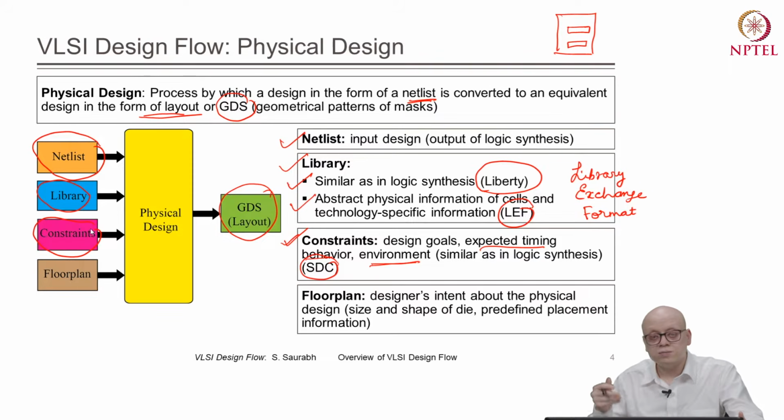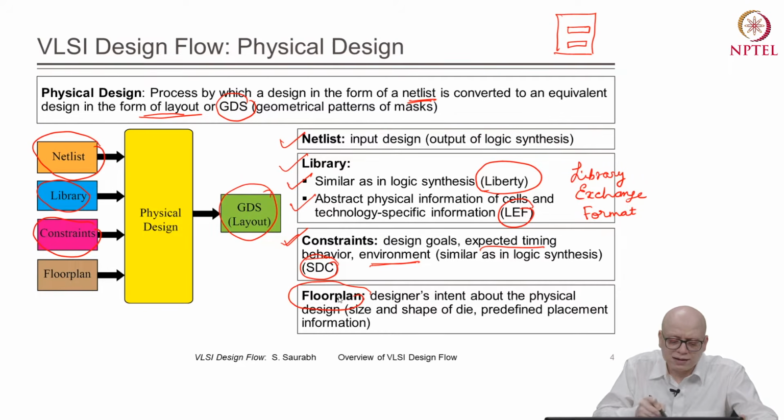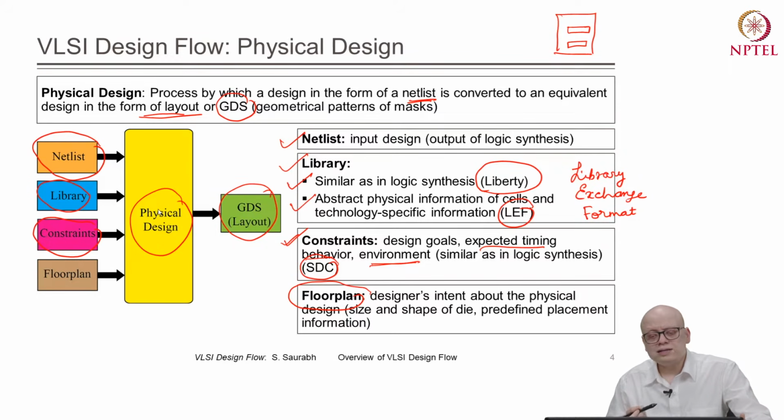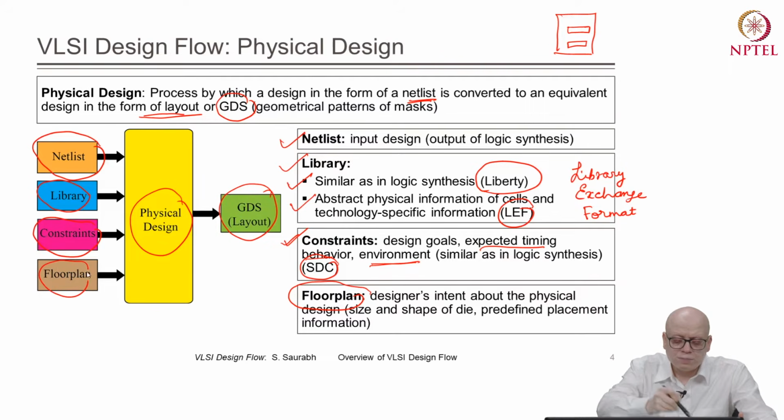For example, we want the input pins and output pins, or input pads, to be located at some fixed location in the layout, or if we want some block to be at a predefined location, we know that those locations are good for physical design. So, those kinds of information can be given in a floor plan to the tool, and these floor plans can be given in a proprietary format that the physical design tools we are using understand. And at the end, taking these inputs, the physical design tool will produce a layout